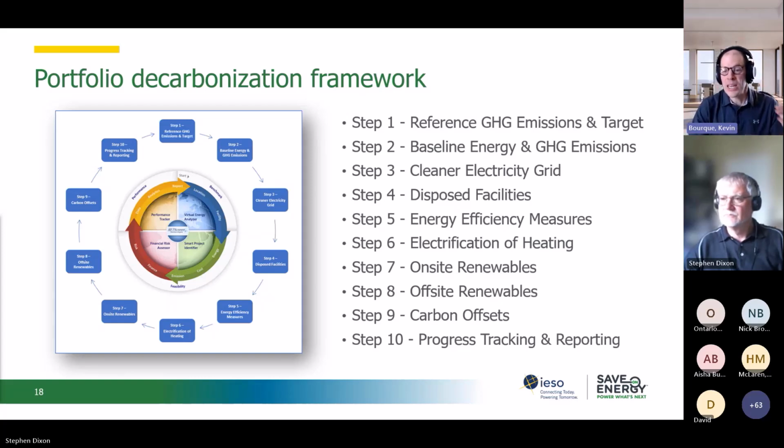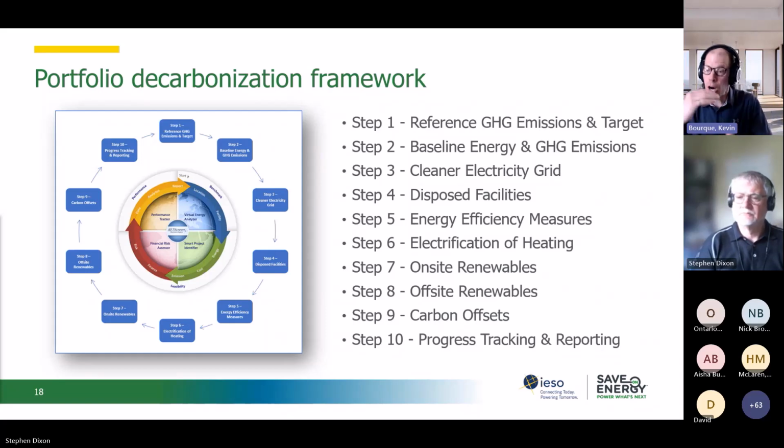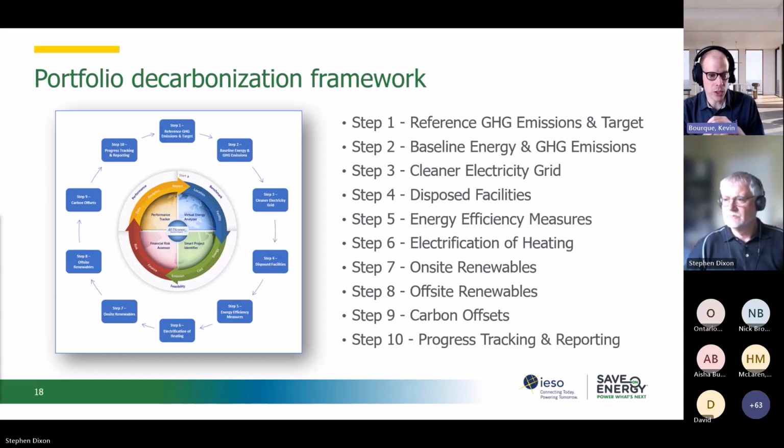So now we've set everything up, and in step 5 is where the net zero planning tool will use the archetypes. Actually, they'll use our deep carbon retrofit archetypes, and this is where we do our energy efficiency measures. So we're going to evaluate the projected impact of all the energy efficiency actions that we're going to take. We are going to use the archetypes in RETScreen, and this is where you engage with the high emitters, the facilities that have a really high intensity, to drive those emissions reductions. And then as part of our energy efficiency measures, there's the electrification of heating. As we all know, heating is very often done using fuels, but electrification of heating, especially in areas where the electricity emissions factor is quite low, can be a very important contributor to the overall net zero targets that you're trying to hit.